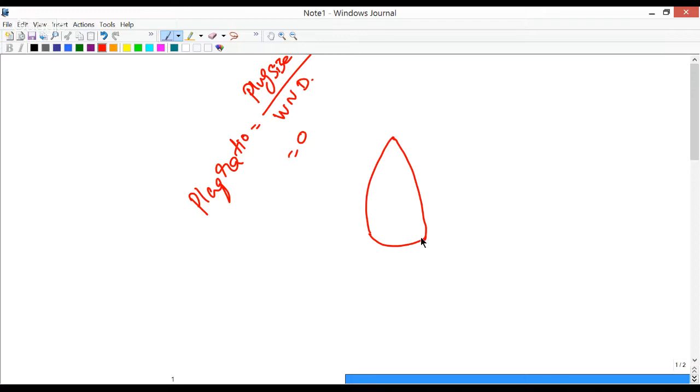Okay, so question number 3 in assignment 3 is, recoil pressure in the keyhole of laser beam welding is due to. So recoil pressure is due to the vaporization of the melt, the principle by which a rocket works. The vapor is actually going up, and it's creating a downward pressure, leading to the generation of recoil pressure in the keyhole.